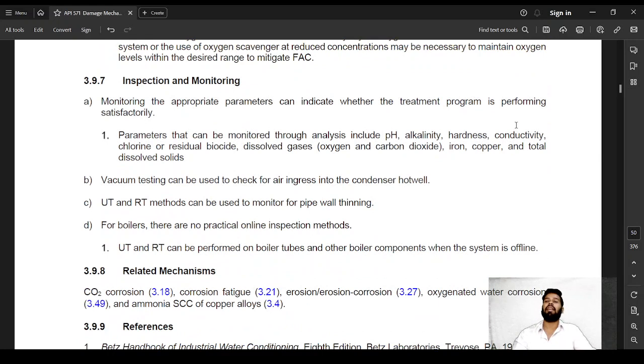Inspection, generally it is going to be wall loss. So wall loss can be identified by profile RT and UT. Generally you would not recommend MT or PT because this will generally happen on the inner surface, which in most cases is not accessible. You can use visual testing, provided there is access where you can go inside the system, or you can do remote VT.